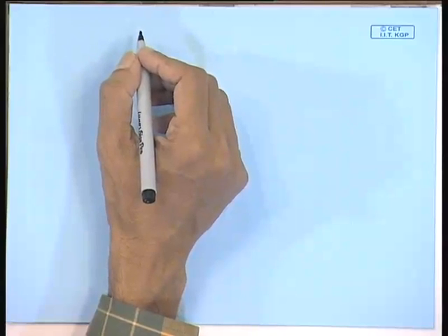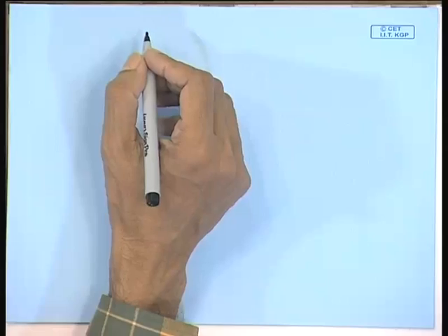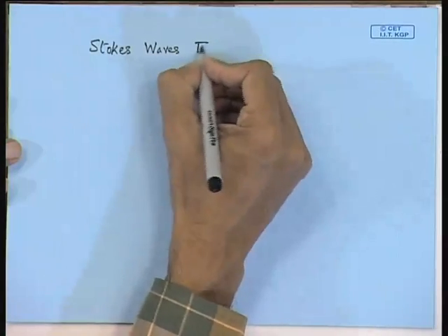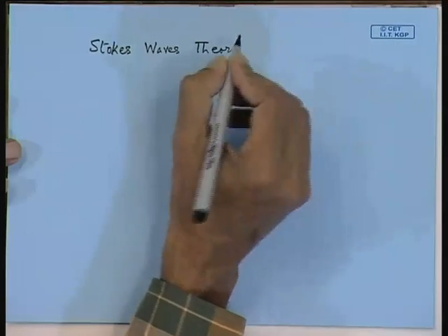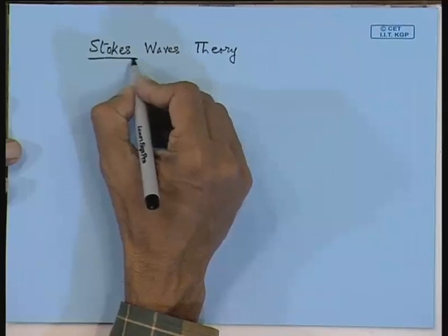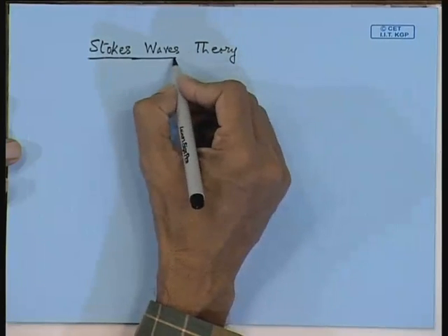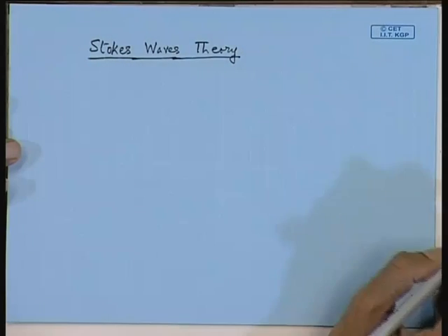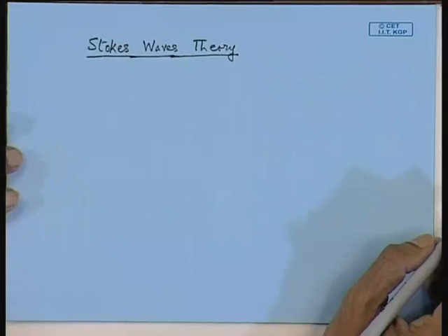So, we have already formulated the Stokes equation. Now we will look at the stream function wave theory. And so, Stokes gives us this for nonlinear waves. When you analyze offshore structures, you look into the diagram that I have given, that is the applicability of all the theories. Do not blindly apply your linear wave theory.